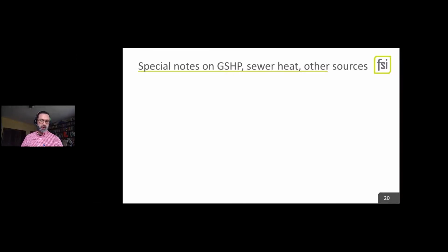So ground source heat pumps are grand, and they have a big upfront cost, and every single analysis we've done on them puts them out at, the shortest I've had is a 20-some year payback, and the longest I've had is more like a 40-year payback. It's a problem, but Duane mentioned PACE loans. You could use PACE loans for anything that's energy improving over baseline code, and ground source heat pumps certainly would be. That's a way to maybe put that cost on the building instead of on the books of the owner.